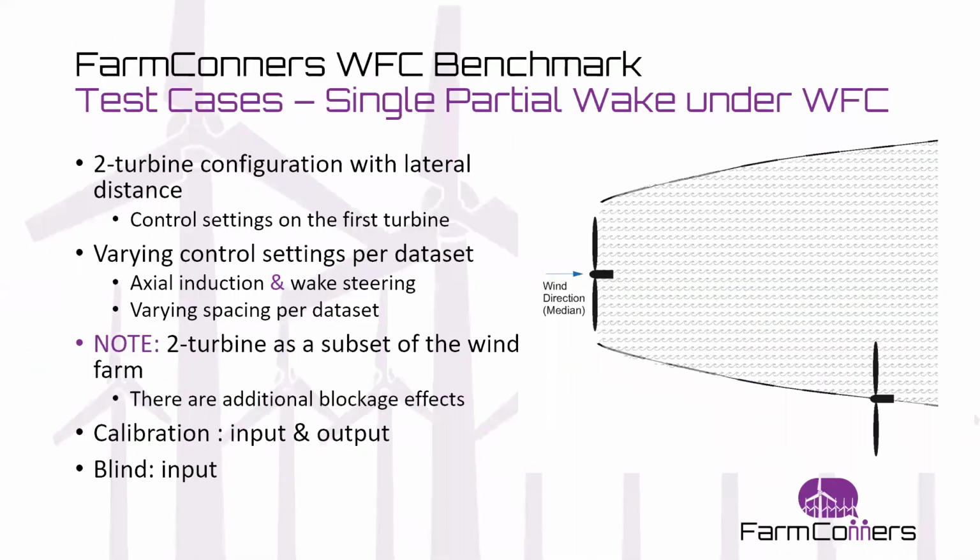The second test case I would like to present is the single partial wake under wind farm control. Very similar to the single full wake case, but this time, as you can see, there is a lateral spacing between the two turbines. Still, the control settings are applied to the first turbine, and they can be different per dataset, still including axial induction and wake steering. The spacing between the turbines, both axially and laterally, can be different per dataset.